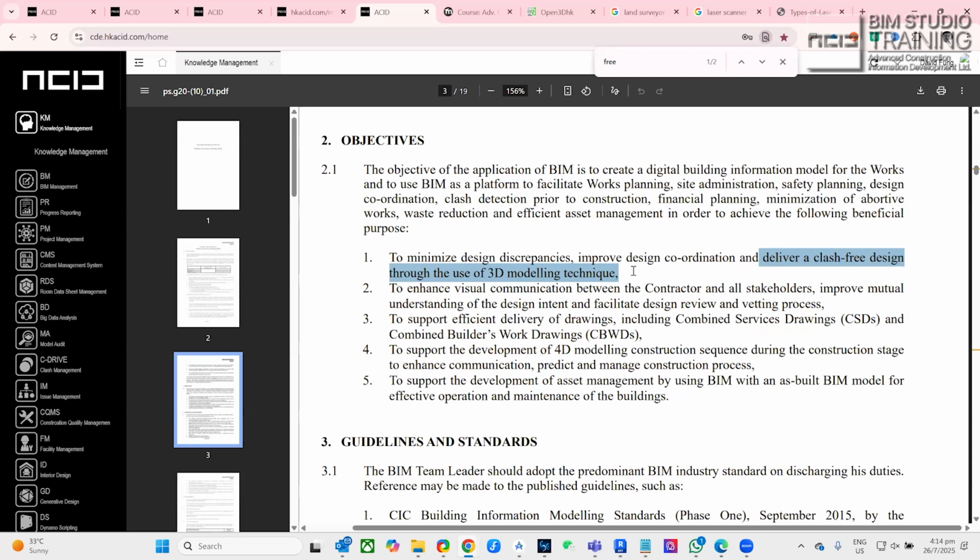Without a structural engineer's calculation, even without a calculation, I know this is possible, because your rebar is 100 mm. Without cutting any rebar, you make a hole, and it is absolutely possible. No need to have a calculation, right? If that's allowable physically or structurally, do you think the structural engineer who built the structural model will be so responsible as to make a hole in their model so that you pass through it and so there's no clash? 100% sure they won't do that.